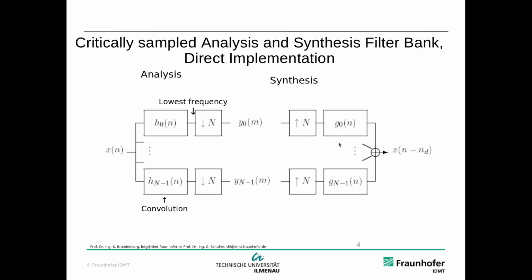And then these bandpass filters basically fish out the correct spectral copy to reconstruct our signal here. So again, we have low pass filter, then many bandpass filters, and here the high pass filter. And if we then add up all those filtered signals, we will get a full bandwidth signal at the original sampling frequency back. So here, ideally this x is identical to this x, but delayed. So we have this n minus n_d, where n_d is the system delay.